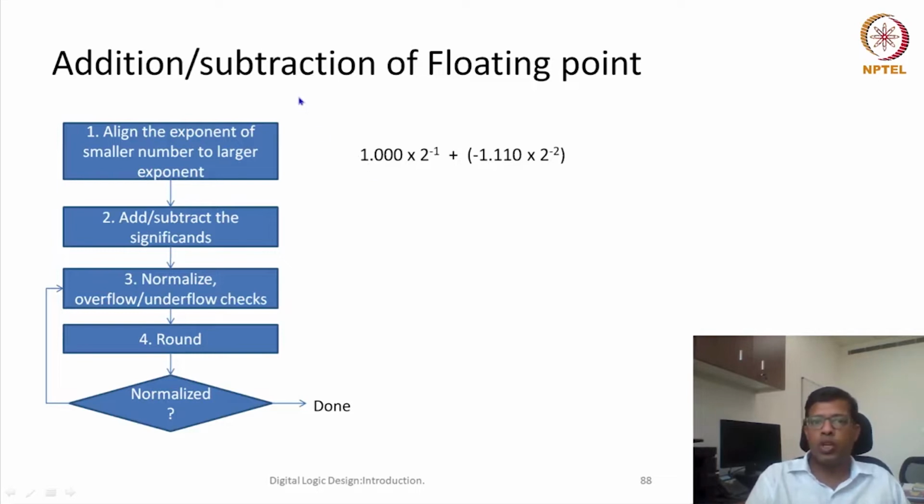So my step 0 is already done, where I have added the significand and extracted the mantissa and exponent, and this exponent is also in the processed format. That means, let us say it was a single precision number, then 127 is already subtracted from whatever exponent I get from that 32-bit number.